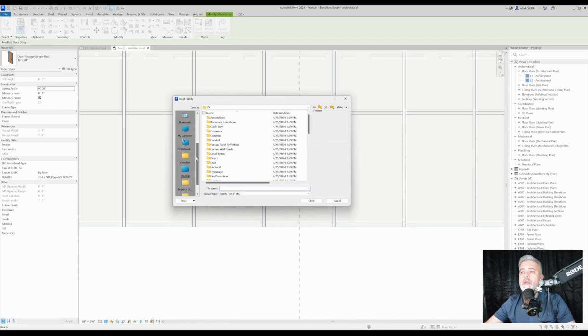In that case, you'd have to have this path folder, and you go to Doors, and you'd have to look and see if you had anything called curtain wall door, whether it's double, whether it's single. And if you select, you get a preview right here. You can see what they look like before you get them. These are the only three out of the box you can get.